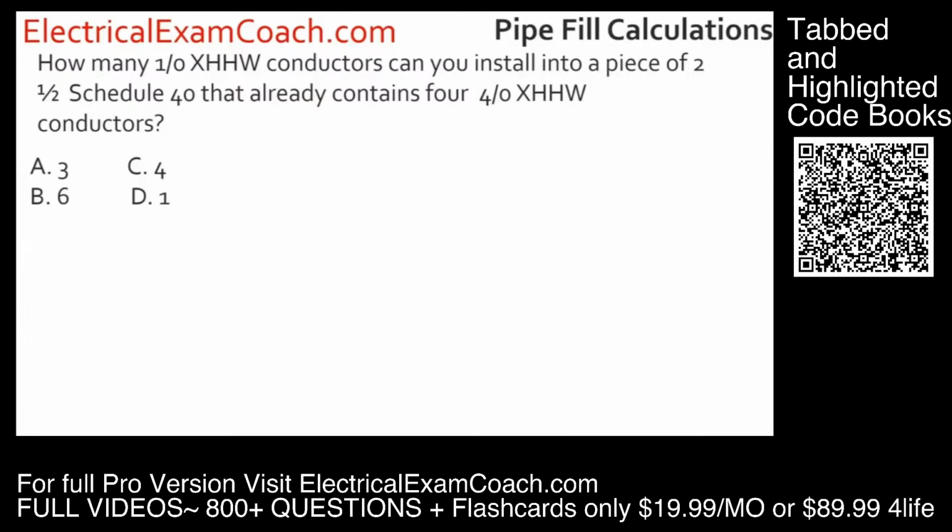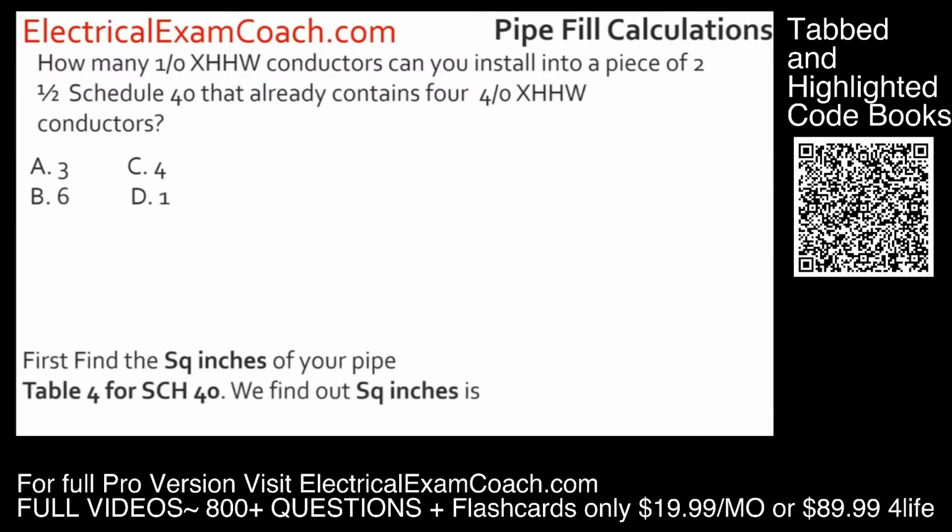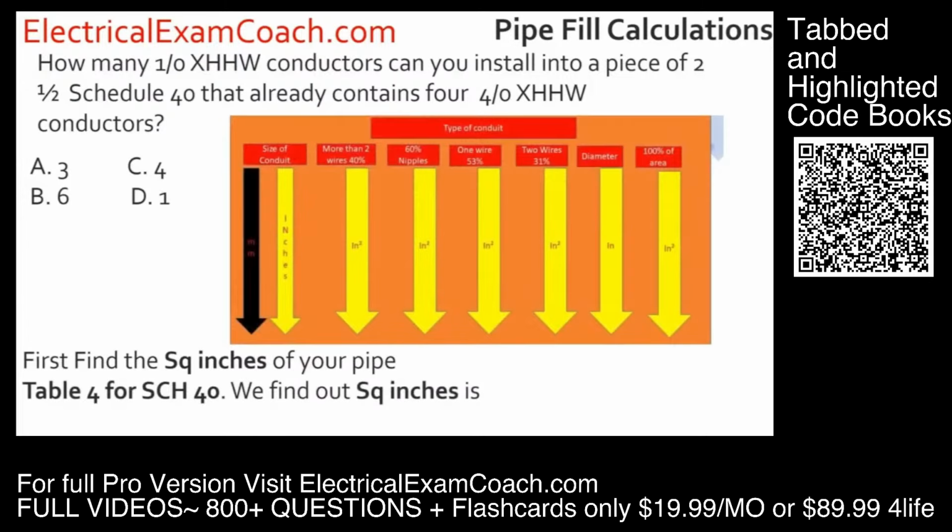How many 1/0 XHHW conductors can you install into a piece of 2.5-inch Schedule 40 that already contains 4 4/0 XHHW conductors? So the first thing we're going to do is find out the square inches of our pipe. For that, we're going to head to Chapter 9, Table 4, for Schedule 40. When we get there, we're first going to verify that we are in the right type of conduit. Then we're going to come over here to the left, find our size of conduit. Then we're going to come over to the 40% column because we have more than 2 conductors. And we're going to find that for this conduit, it's 1.878.